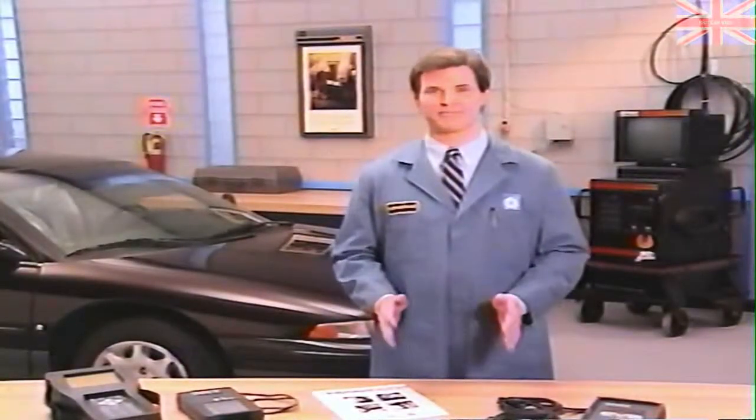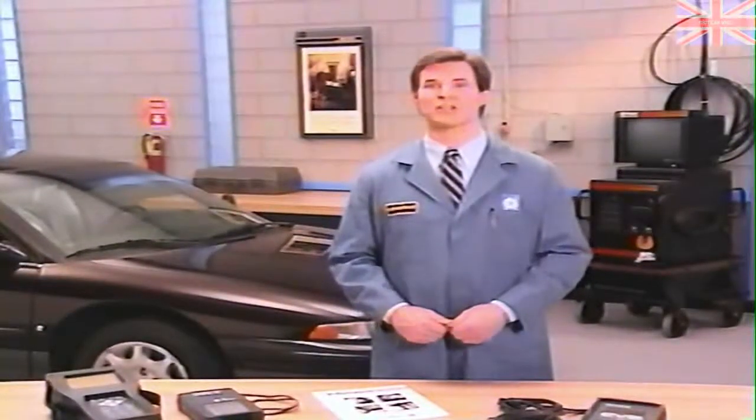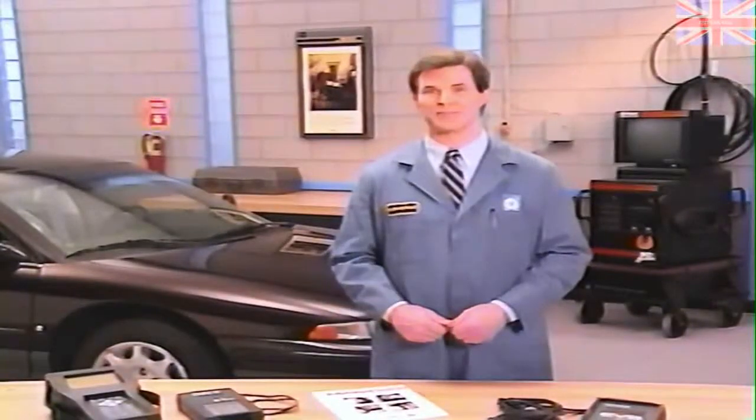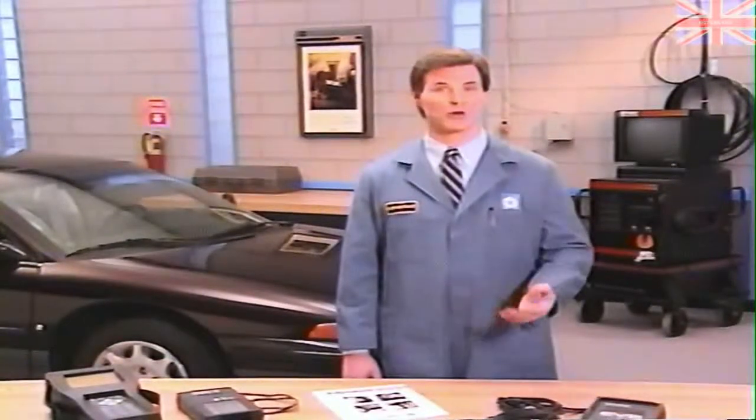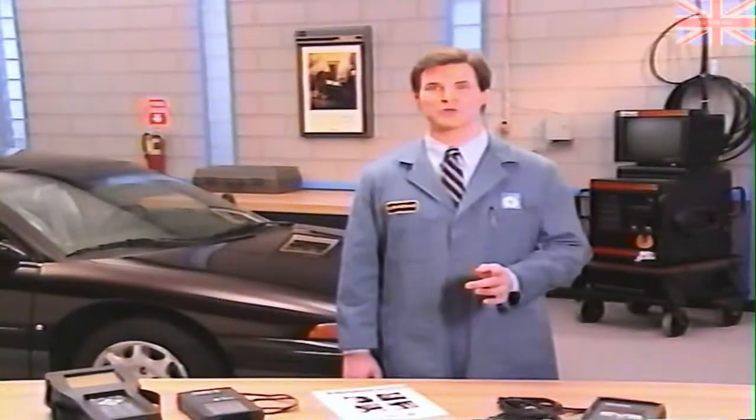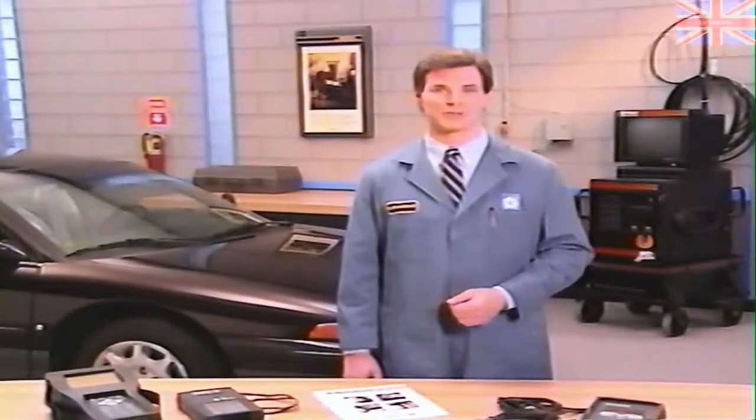Our trouble symptoms are classified as shake. Shake is mainly caused by abnormal conditions in the tire and wheel assembly. The shake frequency and the wheel speed frequency at 45 miles per hour are both 10 Hertz. This further confirms that the trouble lies in the wheel and tire assembly.